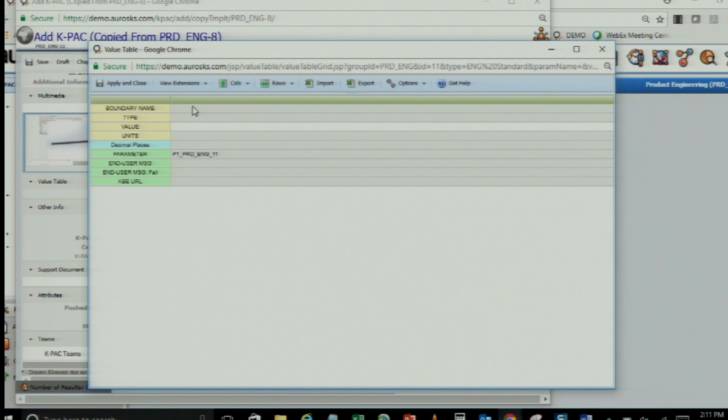So the first thing you notice it's set up as a table. This is a column that represents a specific kind of relationship. So there's two relationships here, not just one. So can you create two columns, please? Okay, now we got two relationships. So the first one is the egress hole. Must be 2 millimeters or greater. Okay, let's say it has to be 2 millimeters. Okay, that's the hole size we want.